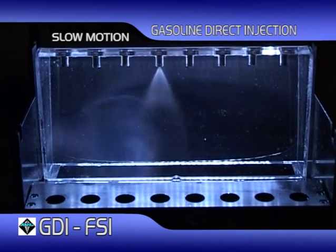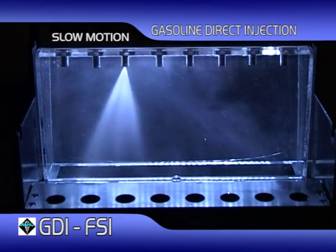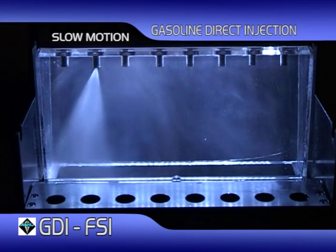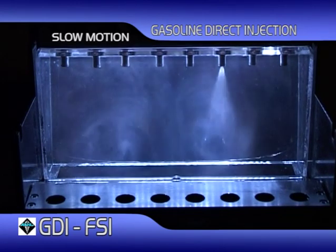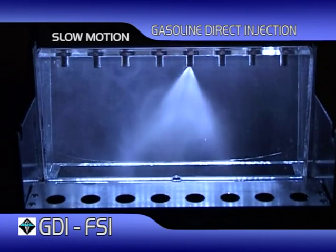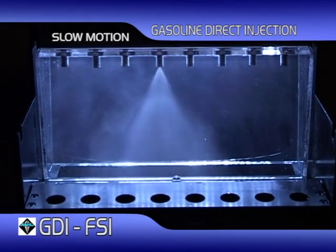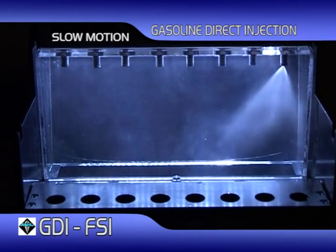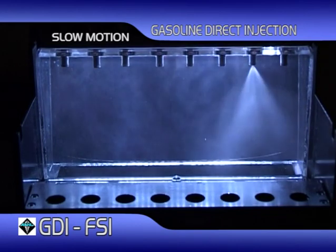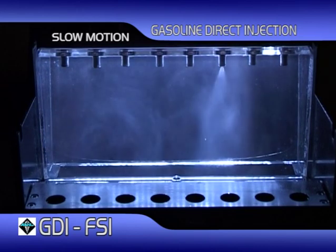If you look closely, you will see different types of spray angles and spray patterns. A visual check of the atomization is also possible to the trained eye. The various vehicle manufacturers all have their own injector designs and have injectors produced to their own requirements. The most critical factor in the GDI injection system is the fuel distribution and atomization. As a shortage of fuel delivery can be easily corrected by the lambda control system, any intermittent changes in fuel distribution or atomization are corrected by the short-term fuel trim as part of the adapted engine management system.